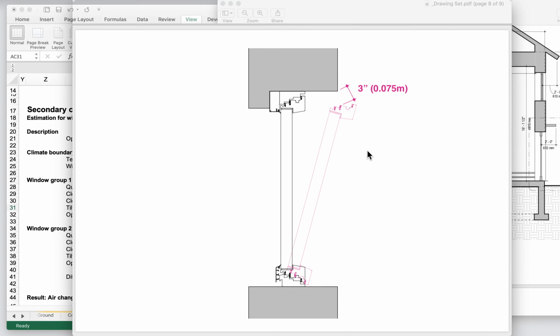And the only way to figure this out is to get your hands on the actual CAD profile for the windows that you're working on, figure out where the hinge position is, and then draw in the open sash of the window and measure the dimension relative to your wall. Depending on the thickness of your wall, the way you trimmed out the window, the position of the window, how the window opens, how high and tall the window is, will affect all of these things.